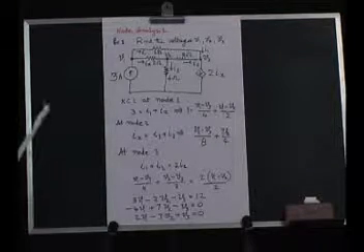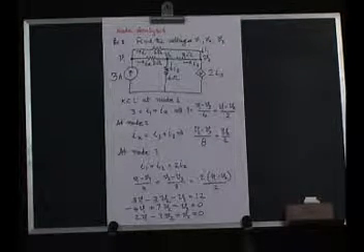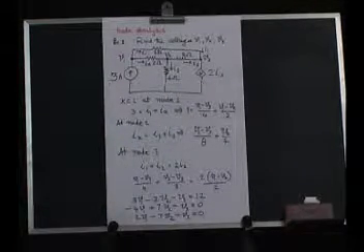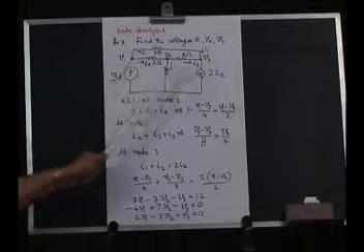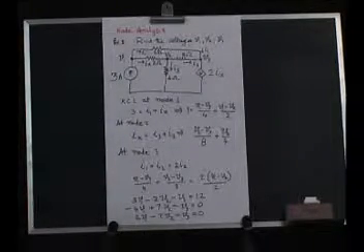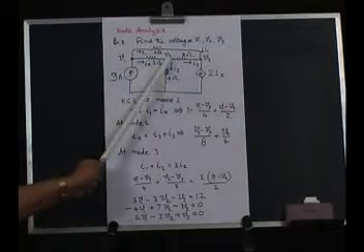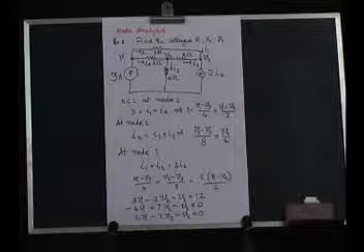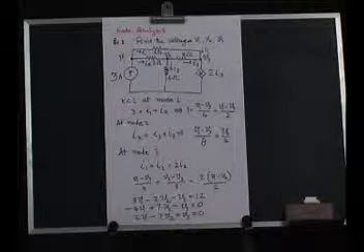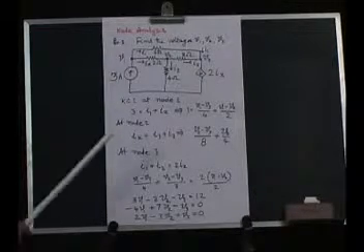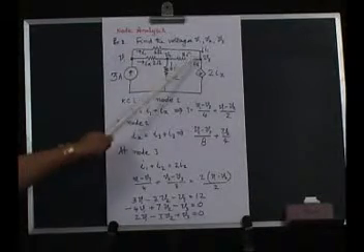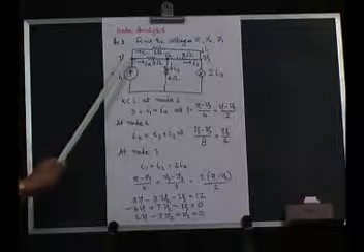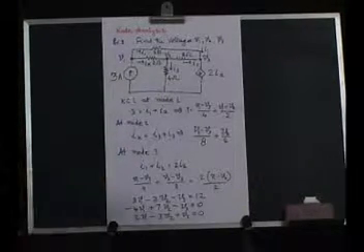Let us take a more complex circuit consisting of a current source, a dependent current source, and more nodes. Earlier we have taken 2 nodes, now we shall take 3 nodes, V1, V2 and V3, apart from the datum node or reference node. Now, the technique is the same, whatever the circuit. For instance, we have 3 nodes here, so we have 3 equations. That means we apply Kirchhoff's current law at the 3 points 1, 2 and 3.